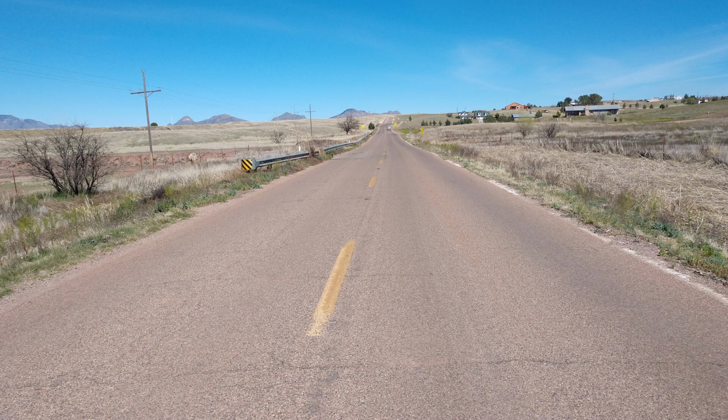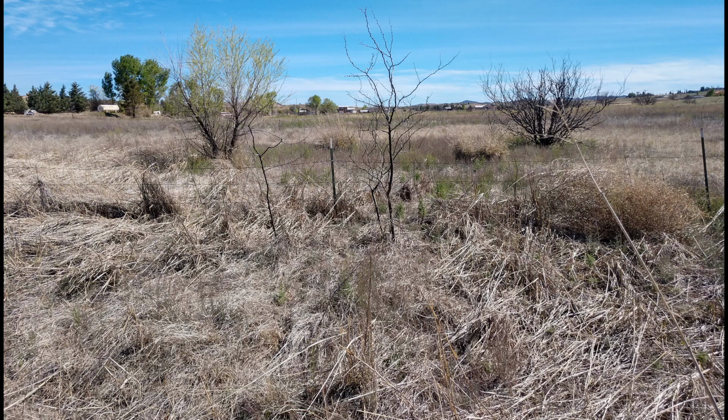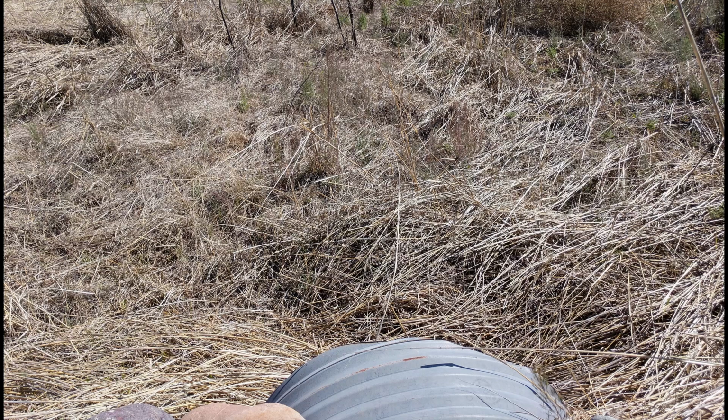Let's walk across the road and look upstream. Here's how the drainage appears on the other side of the road, looking upstream of the culverts. The drainage is a beautiful and diverse wet meadow wetland. Look at the wide floodplain with no stream channel and no erosion. The culverts have provided permanent vertical grade control, protecting the wet meadow upstream of the road by not letting the head cuts move under the road.